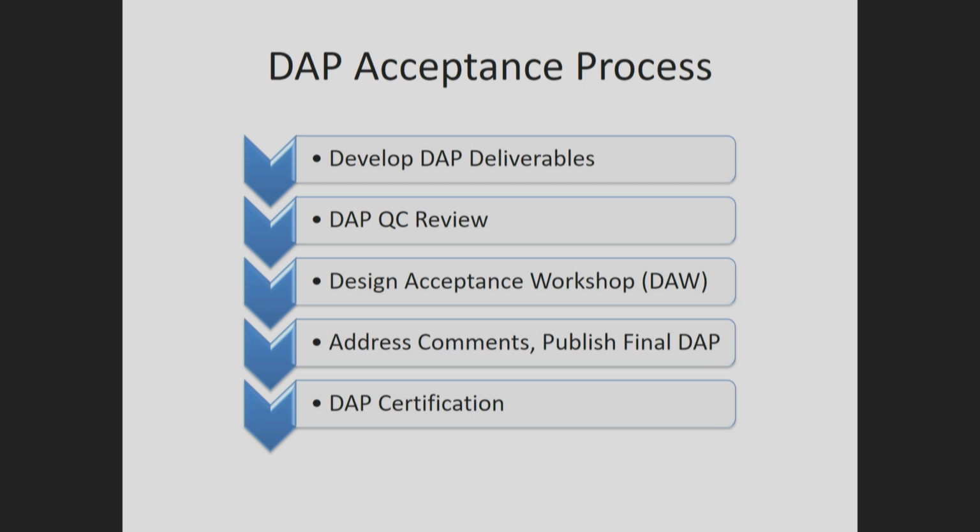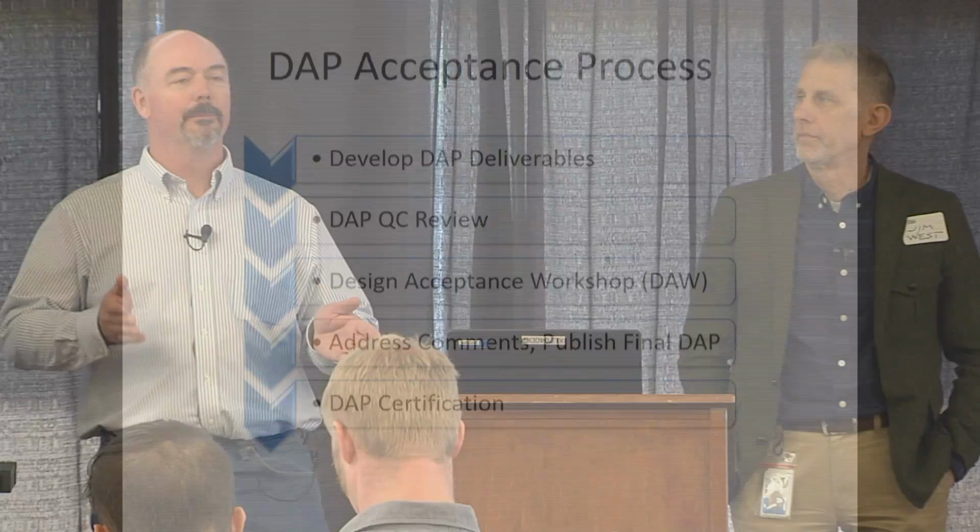And so also, this is one of those things in the past that it was pretty easy sometimes to pencil whip. You just go, yeah, it looks good enough. But say this happens during construction season and your assistant project manager or construction coordinator has been out paving all night. They're not that crazy about coming in during the day and reviewing plans and giving comments. And so sometimes you slide past that. Well, you can have a real constructability issue develop during that project, and you can carry that forward if you're not taking a good look at the plans before that workshop.